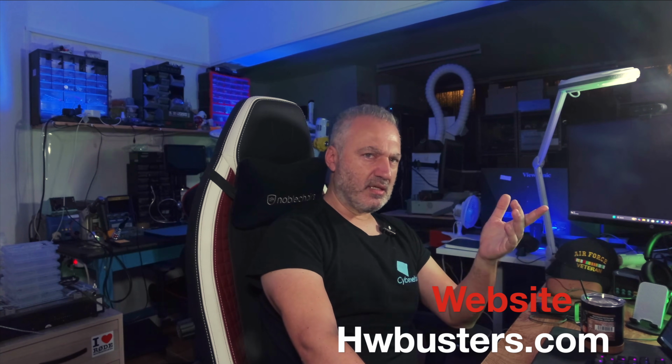This is the key. BAI is not about edge cases. It measures performance where your system actually lives: idle, desktop, light load usage, not full load. And that's a huge shift. Now, here's where it gets interesting. Burst behavior creates rapid power transitions. This stresses transformers and inductors, and that produces coil whine. BAI doesn't measure sound, it measures the cause behind it. That's why high BAI means higher coil whine risk.